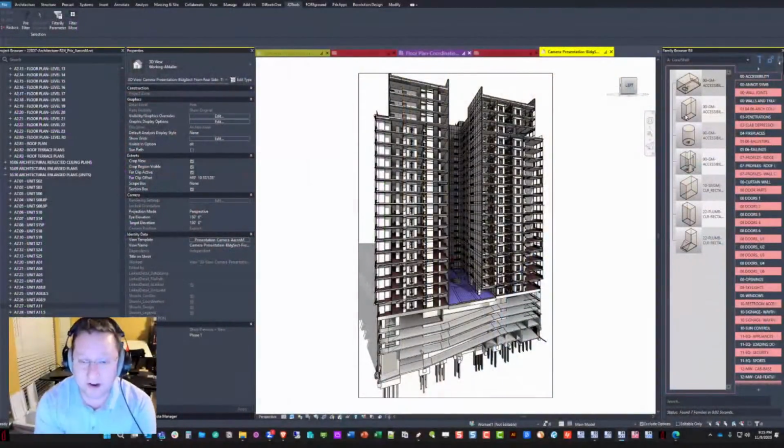That's a great question. We will do different unit types Revit wise. So there might be an A1 9 feet and an A1 12 feet. In the model group tag, they might both just say A1. And if the schedule is sorted by type and not itemize every instance, they'll both schedule as A1. But for me, it's super important. A 9-foot ceiling and a 10-foot ceiling aren't the same. You could shortchange that in Revit to save yourself like 10 minutes worth of time, but then you miss some coordination issues.